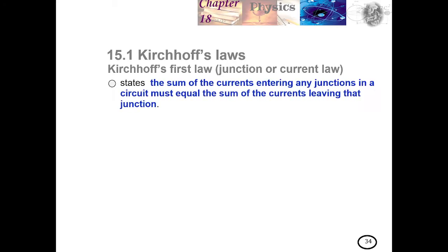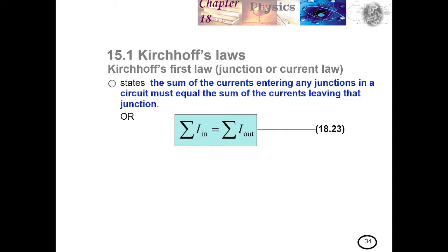It states that the sum of the current entering any junction in the circuit must be equal to the sum of current leaving that junction. Or in mathematical form, the summation of I in, the current that goes in, equals the total of the current that is going out. So actually it's very analogous to water.